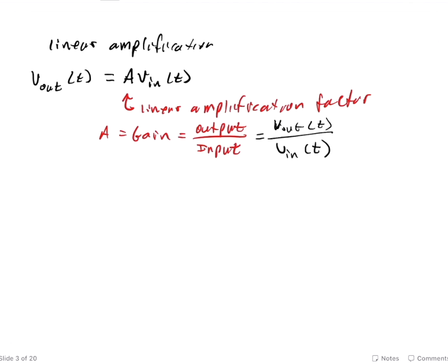But we usually deal with voltage gain in this course. And we are usually working with low levels of voltage, usually microvolts or millivolts. And that introduces a big simplification later called small signal analysis. Small signal analysis takes inherently nonlinear circuits and turns them into linear circuits, and analysis becomes very easy. Just resistances, voltages, currents, maybe a few capacitors here and there.